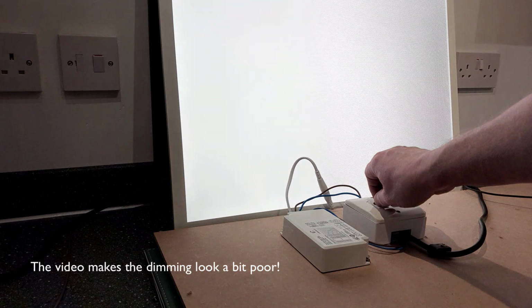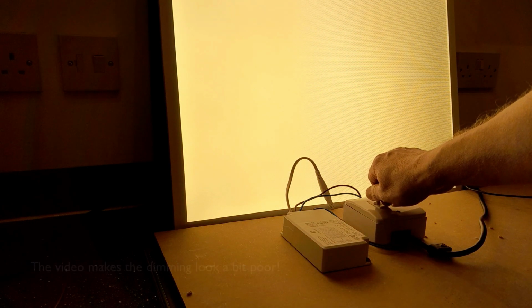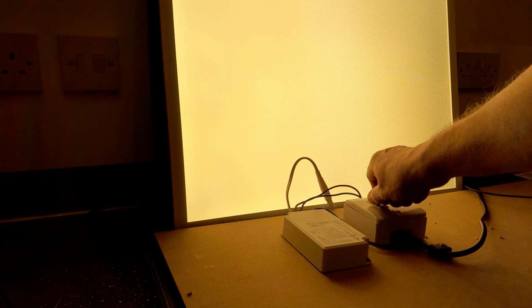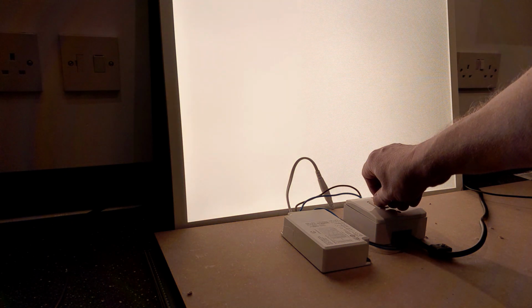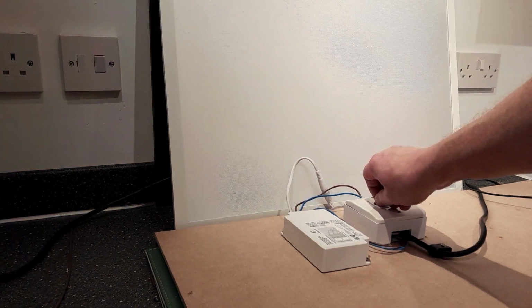As for the maximum amount of panels you could have on this module, for example, I contacted the manufacturers. They didn't give me a number of panels. They recommended using a switch on the dimmer to switch a relay rated to the appropriate inrush of the fittings. This module is only rated to 6 amps.